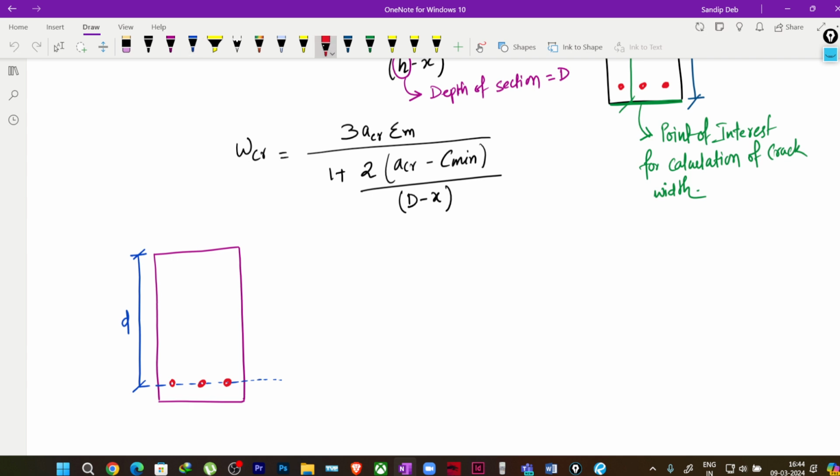Okay, now if you draw the neutral axis here, suppose this is my neutral axis, N. Correct? So what is the depth of neutral axis? From the top compression face, this is my depth of neutral axis. Now see, it can be at the top also, because suppose you have hogging, so it will be just the opposite case, correct?